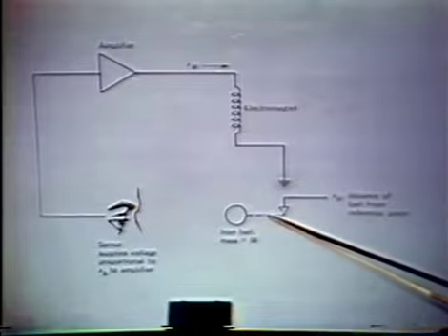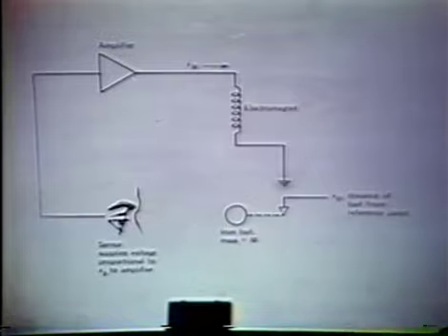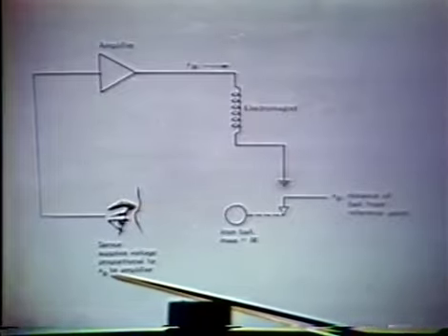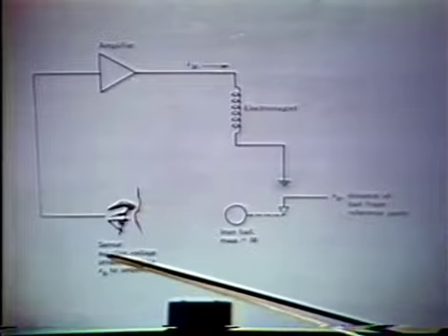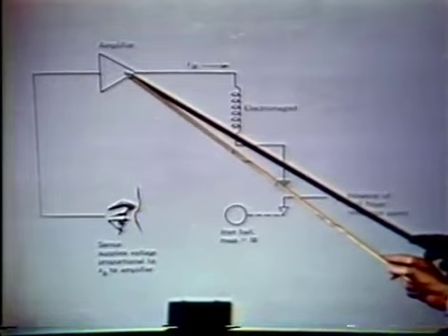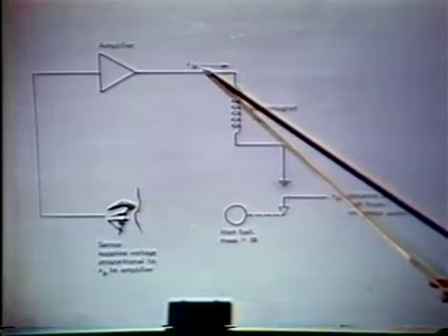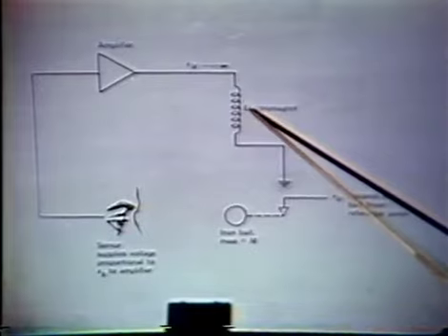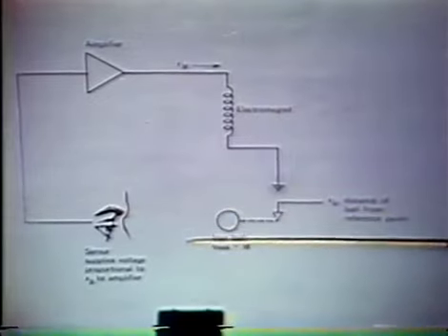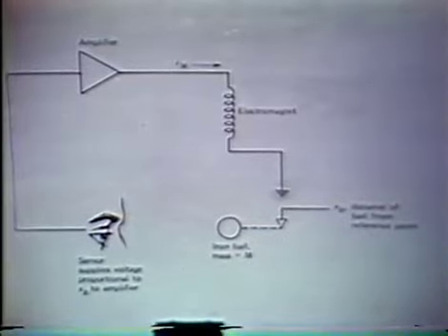We observe the position of the ball, actually not with an eye, but rather with the photocell lamp combination that I described a moment ago, and get a signal proportional to the ball position, x sub b. We take that electrical signal and amplify it, and as we'll see, we have to condition it as well. That amplified measure of position generates a current, which we then use to drive the electromagnet. And as I described earlier, the strategy is, as the ball moves down, we increase the strength of the magnet to pull the ball back toward its equilibrium position.